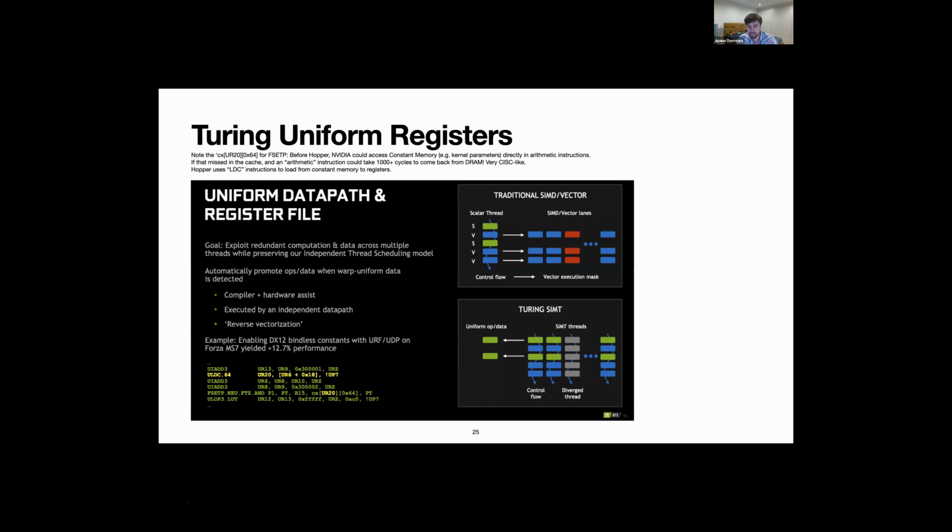So we implicitly touched on uniform registers as part of looking at the SASS. I don't think there's a lot of extra to say there. It's obviously a power benefit. It's not as much of a performance benefit in my experience, partly because of that 1 instruction per clock bottleneck. As far as I understand it, an instruction like LDC here that loads a constant into a uniform register, even though it's not using most of the resources of the SM, like the register file, it still takes a scheduler cycle, I think.